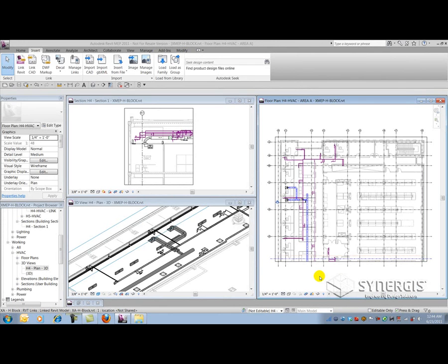In Revit, you might experience a variety of different interoperability issues with CAD formats. In this case, I was working with a customer whereby they were using AutoCAD Plant 3D and Revit MEP to do their building model project. The process piping was done in AutoCAD Plant 3D while the other MEP systems were produced in the Revit MEP model. The architectural model was created in Revit Architecture and provided by the architect. It's linked into the Revit MEP model we see here.